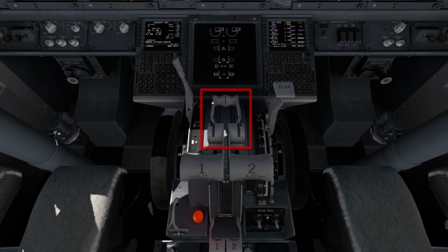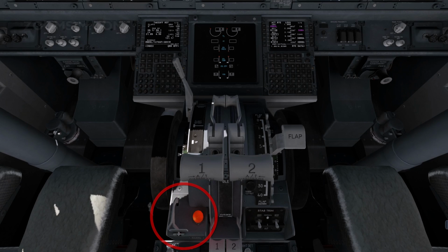Reversed thrust levers, down. Forward thrust levers, closed. Flap lever, set. Set the flap lever to agree with the flap position. Parking brake, set. Verify that the parking brake warning light is illuminated. Engine start levers, cut off. Stabilizer trim cutout, normal.